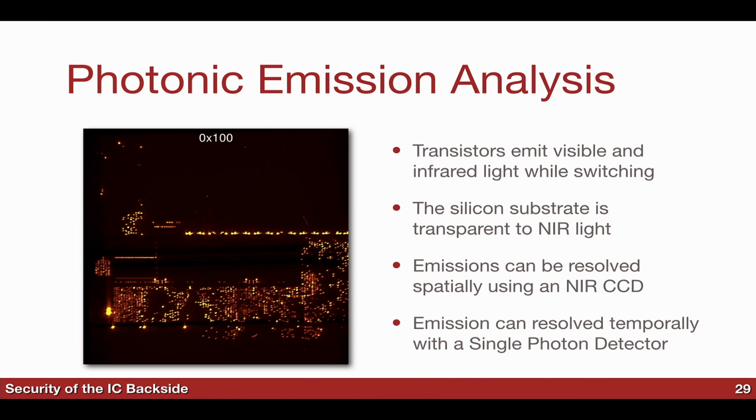What this actually is: you take an infrared camera and you let it watch your chip as it executes data. You can actually see the photons that the transistors emit, because with a certain very low probability, a transistor that switches emits photons. But if you sit there with your camera and repeat this operation many times, you can get an image like this.